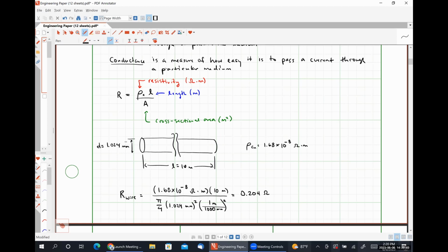The 220 is technically a little bit brighter. You get the brightest response out of your LED without running the risk of accidentally burning it out by passing too much current through it. So generally speaking, we are going to be using resistances on the order of tens to hundreds of ohms.